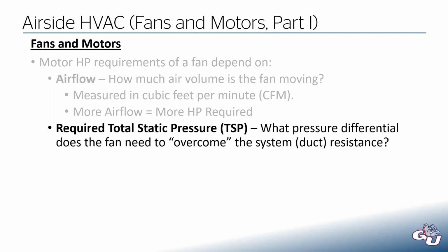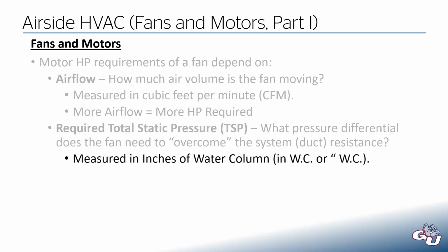What will it take to move a certain amount of airflow from the start of that fan through the ductwork, through the space, through the return duct, and then back into the unit? And so this is typically measured in inches of water column. You could measure it in other pressure units, but in the calculations we use in this industry, it's always in inches of water column.